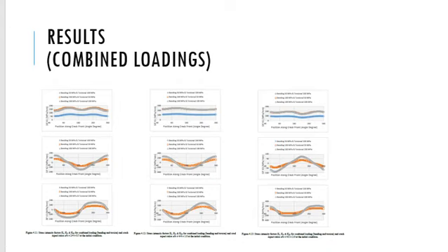It is shown that the largest value of K1 is found at the combination of bending loading with the smallest torsion. In all cases, the largest value of K1 is found at the position of 90 degrees, which has the largest crack depth. For all cases, the larger value of K1 is found along the position along the crack front. It confirmed that there is no effect of bending on the K2 and K3 values, as the values coincide.